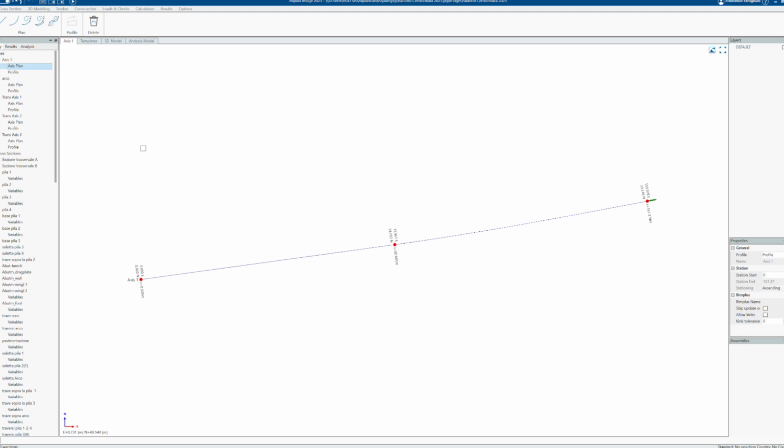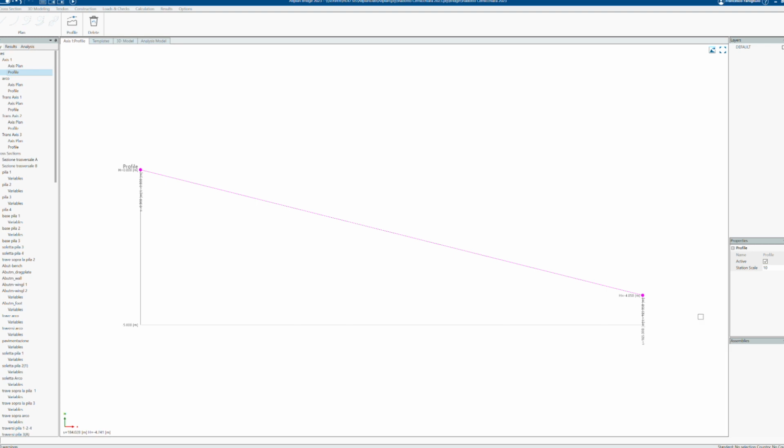Now, as you can see, the axis is identified by 3 characteristic points with fixed coordinates that define its shape and its development in space. The height instead is defined by the profile. Setting up a double axis system is of course clearly necessary when working both on the planimetric and longitudinal aspect of the arch.